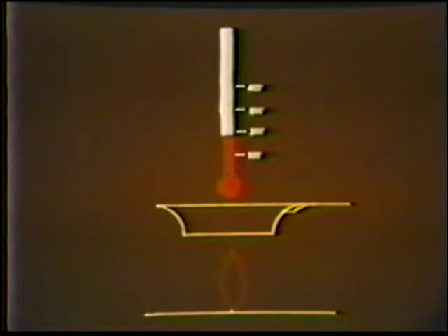This is similar to adjusting the flame of a stove under a pan. The greater the gas flow, the more heat goes into the contents of the pan, even though the flame temperature hasn't changed. When welding with too little gas flow, the rate of heat input to the work is too low, and this produces a narrow weld bead with occasional loss of the puddle. The heat is conducted away, keeping the weld area too cool, in spite of the fact that the flame itself is hot enough.